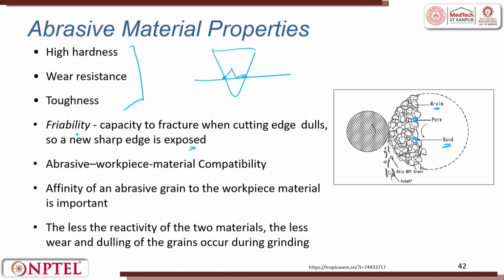So, you will have many cutting edges. Friability is the property of fracturing. Then abrasive workpiece material compatibility is also very important. The affinity of the abrasive grain to the workpiece is important. It should not diffuse, so that no material from the abrasive gets into the workpiece. For example, the abrasive should not dig in and stay there.